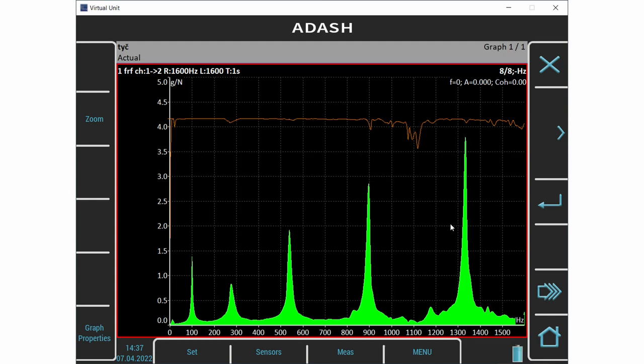And that is the reason why we use FRF measurement. We want to know the resonant frequencies. For example, we need to know the resonant frequencies of machine frame. Any of them must not be equal to the machine speed, because the small force would excite high vibration, and the force on speed frequency, it is the unbalance. It means small unbalance could cause a high level of vibrations.